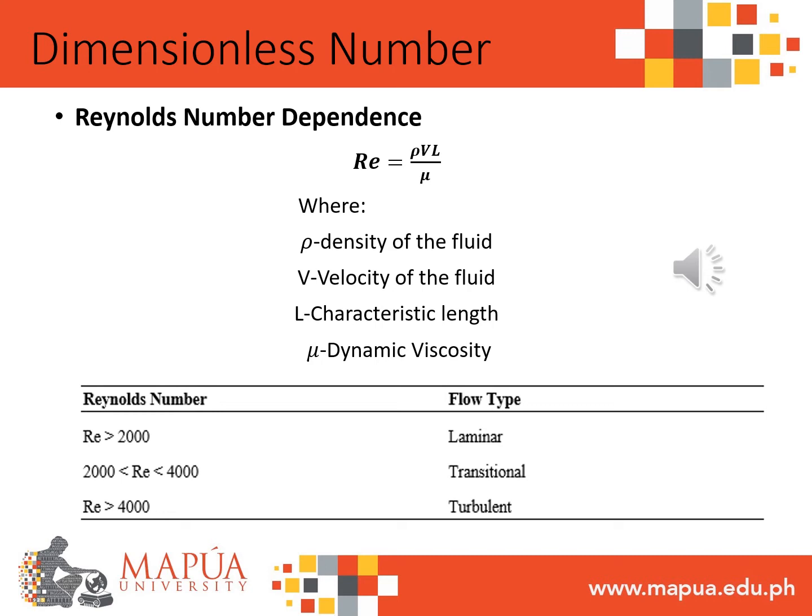When the Reynolds number is very small, the viscous force is more predominant, and correspondingly shear stress will be large and thus friction drag induced will be high. The opposite happens when the Reynolds number is very large. Beyond Reynolds number of 1000, the friction drag becomes negligible. In application to our study, since the ground vehicle operates at a higher Reynolds number, form drag is more significant than friction drag, and therefore our first priority is to reduce the form drag.